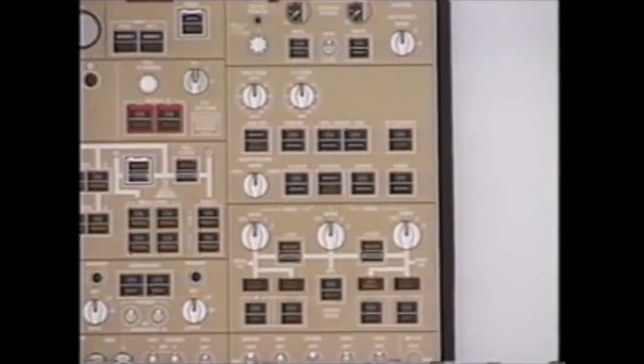The humidifier will not activate until the FMC top of climb and will continue to run until 2 hours prior to the top of descent. If your top of descent is within 2 hours of top of climb, the humidifier will not activate. However, in order for the humidifier to shut down, it needs to know the top of descent point. Thus, if the approach is not installed, there is no top of descent point. The humidifier will run until it can calculate that point.